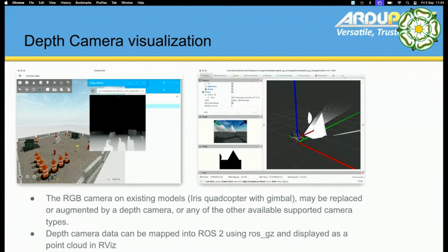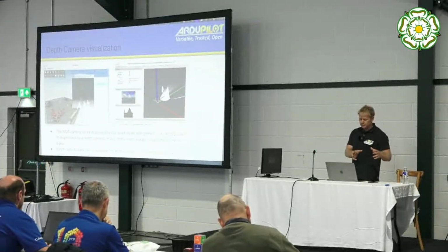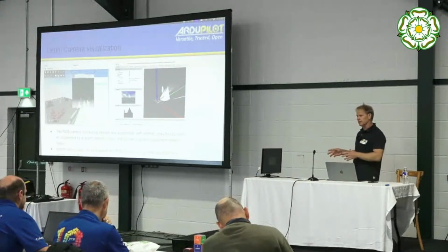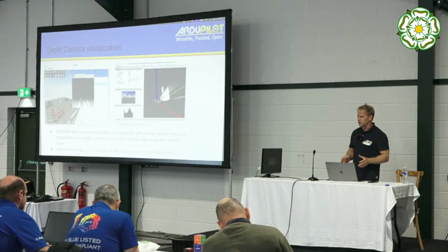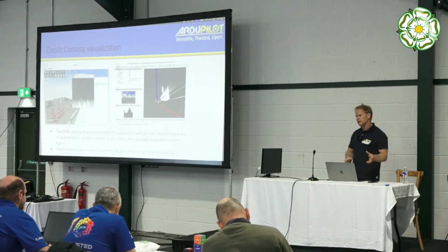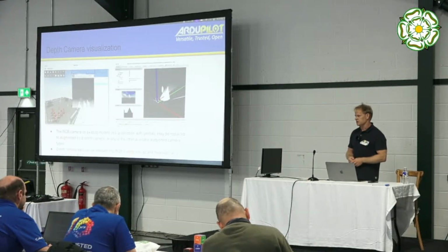And the tools for doing this are not tools that we write. So ROS-GZ is again an Open Robotics Foundation library, but it allows you to pull data from Gazebo into ROS. But we also use it for pulling data that we generate on the flight controller and publish out through DDS into ROS as well. So there's lots of tools there for getting data into the toolset that you are interested in using.